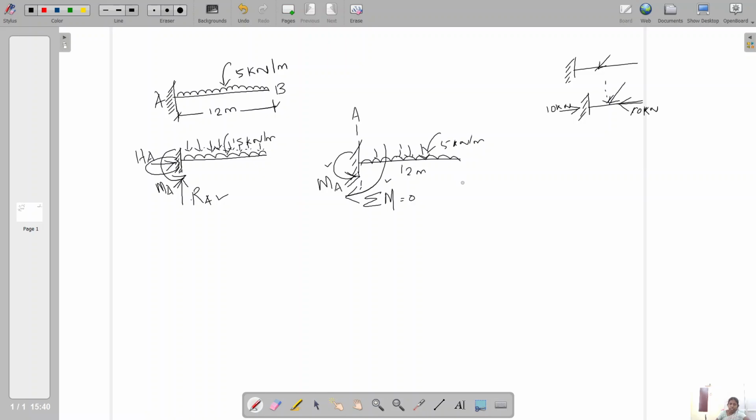First of all, I am considering the direction of MA as positive, because the equation equals 0, so any minus sign or plus sign will counteract each other. So I am considering MA as positive, which is anti-clockwise, so the clockwise direction is negative. While writing the moment equation, MA should not be multiplied with any distance, because MA itself is a moment.